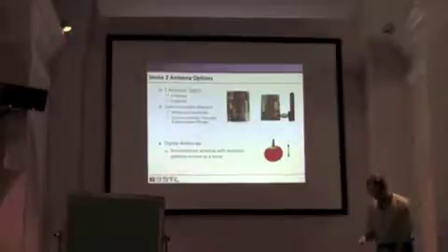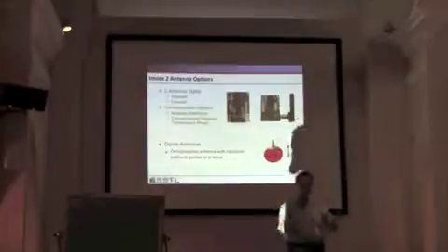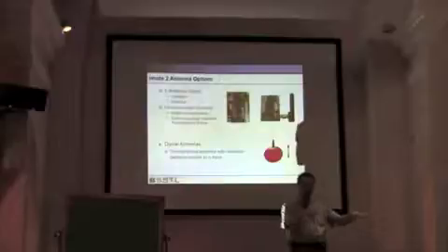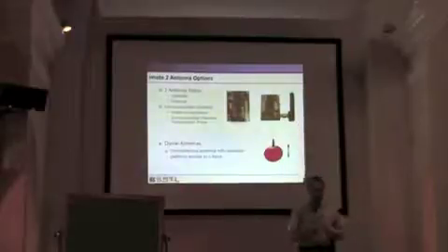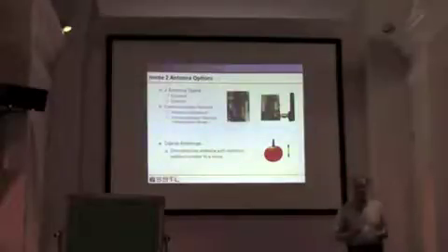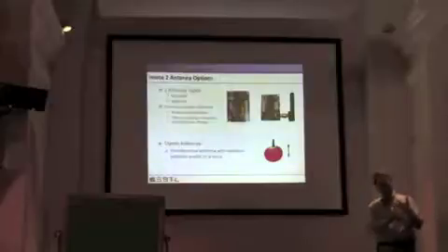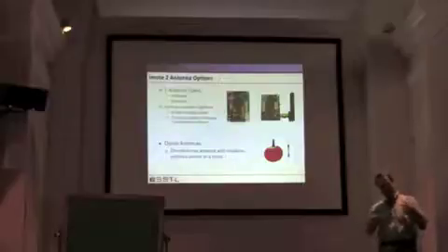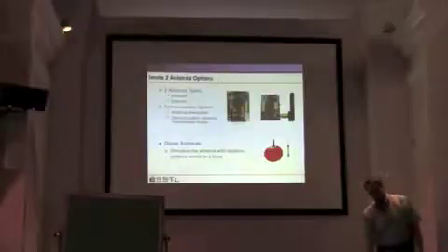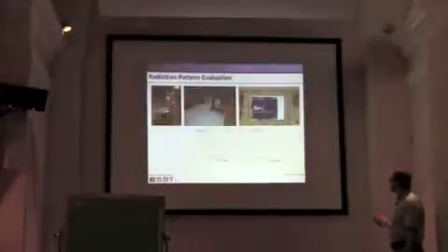One of the reasons was that the first student that worked on this, Tomonori Nagayama, took the sensors out and put them in the grass in the lawn outside of Newmark Laboratory, and then he walked back to see how far he could receive the signal. It was about 30 feet. Not very good at all. Well, we found out later, because we hadn't done anything in this, that grass, leaves, the water in the grass, the water in the leaves blocks the signal. Plus you have ground effects, the radio waves bouncing off of the ground. And so we found that understanding the performance of the antenna was very important.